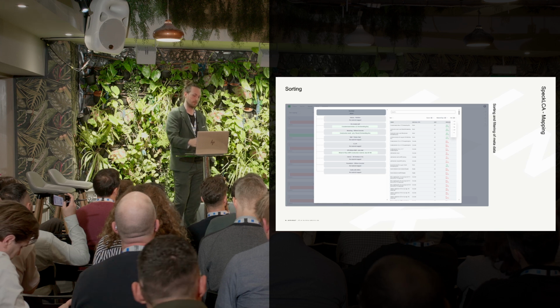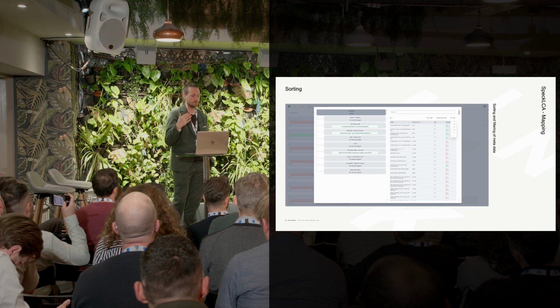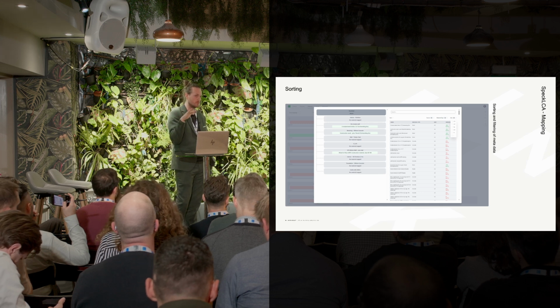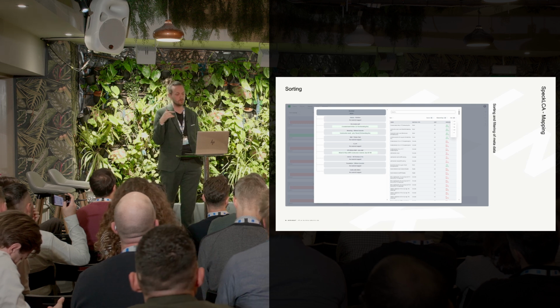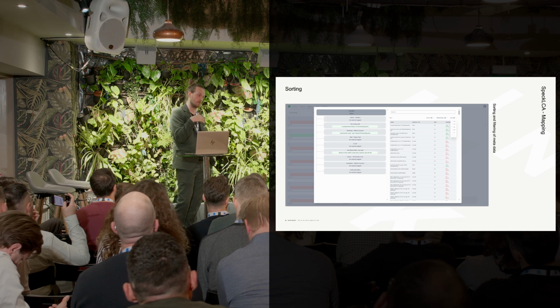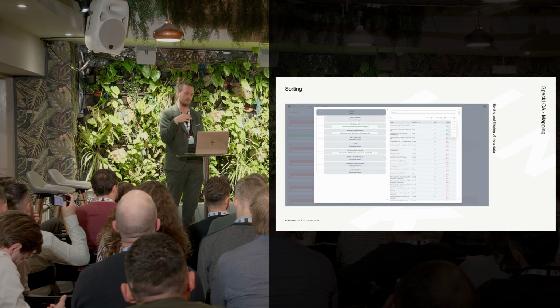So this is how you can find that you only want materials that you can map towards cubic meters or something like that. And when you apply the material, it's going to use the quantity that exists in the model and on that object. So if you use a cubic meter material, it's going to use the volume. And if you use a square meter or a meter, it's going to use the length and so on.